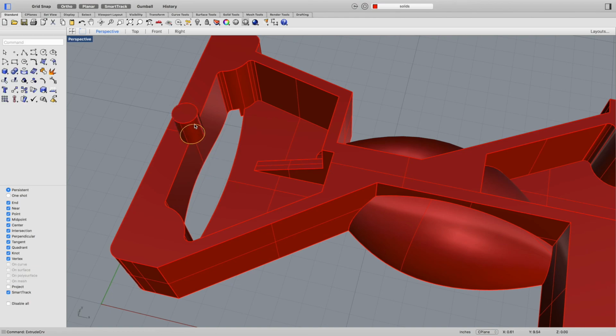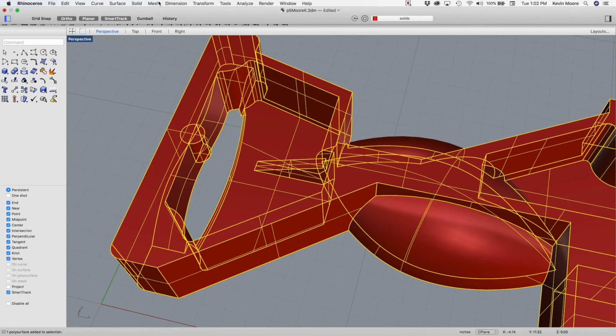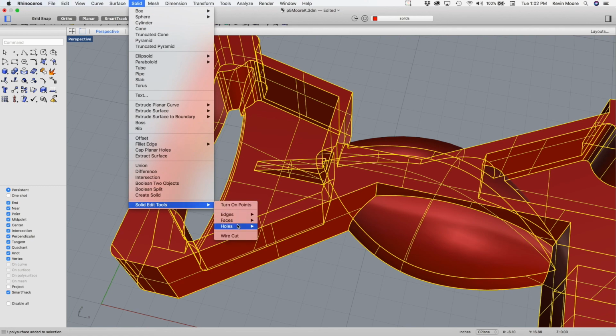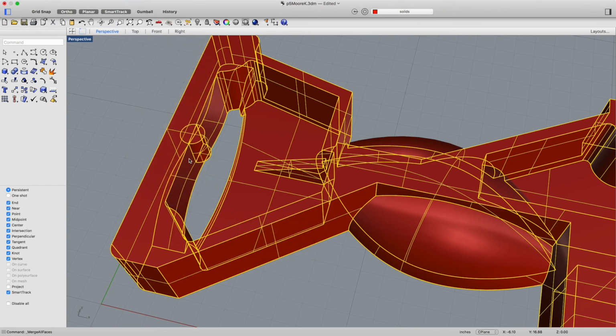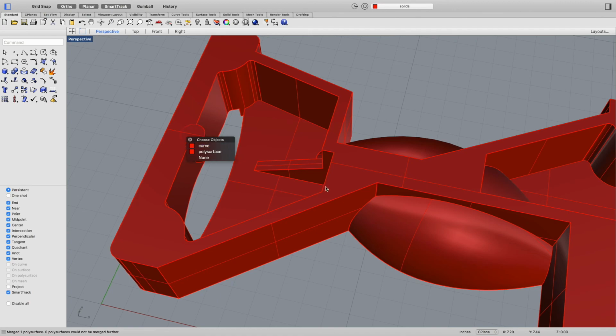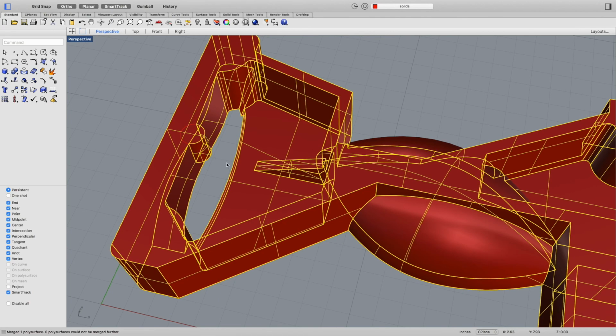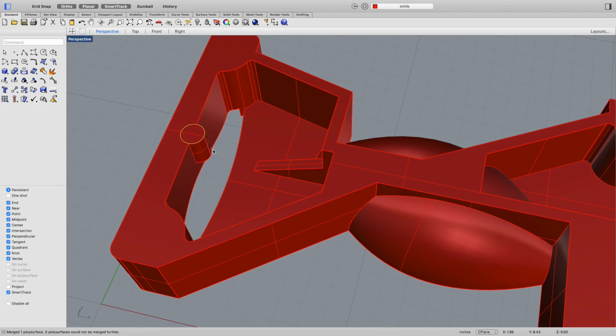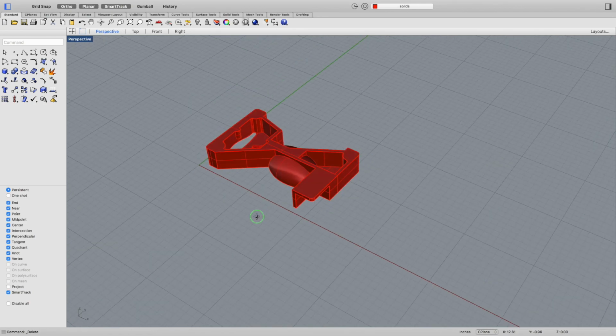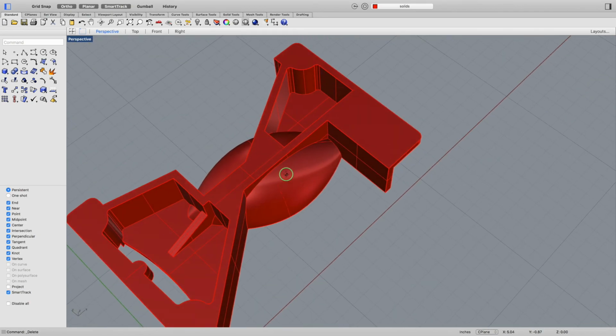1.5, enter. Whoops, that went up. Delete that. XT, enter. Down, negative 1.5, enter. And then Boolean union, this to this, enter. And once again, solid edit tool, faces, merge all faces. Click here, delete the curve. Oh, nope. Click here, curve, delete. Okay, that gives us our whole shape.